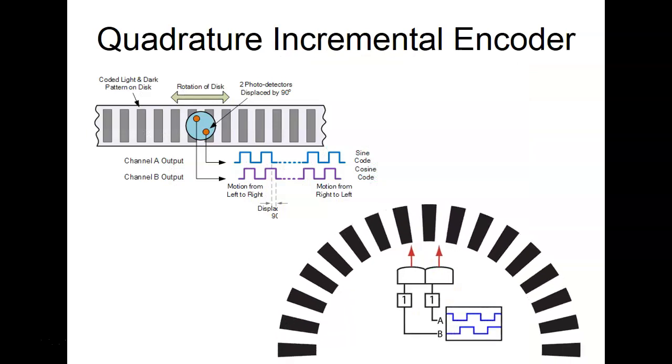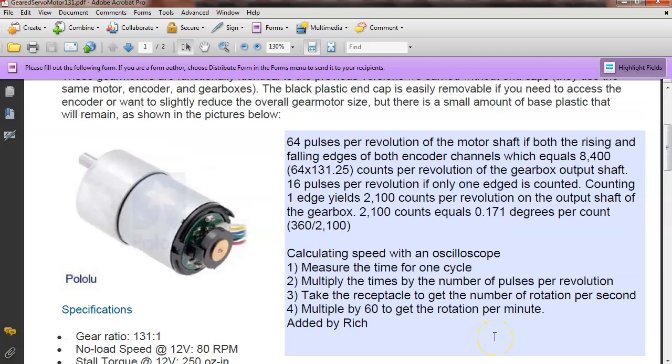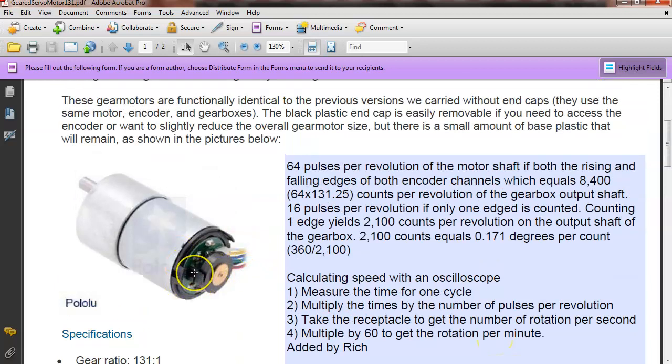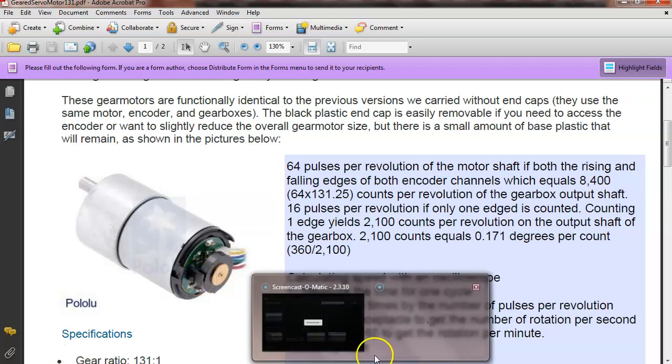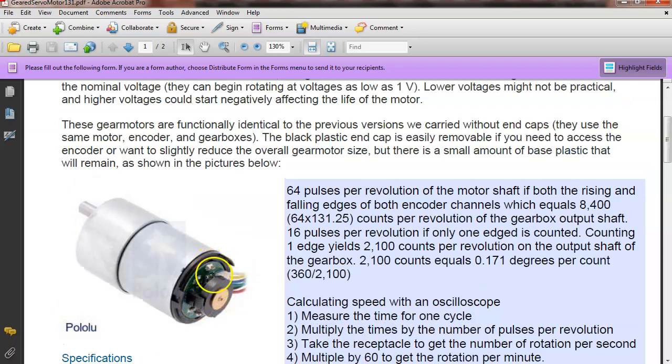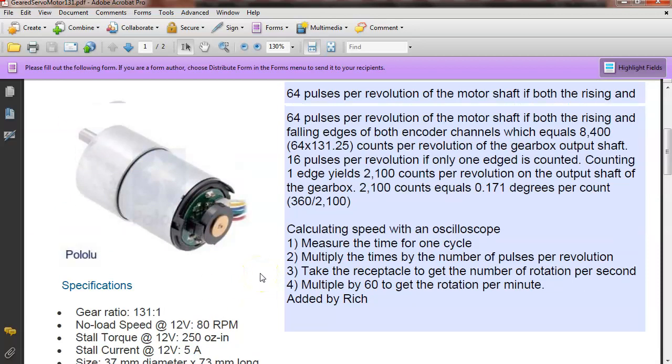This is the signal we discovered here. It's using Hall effect for the encoder. We'll look at that. That's one of the things that senses a magnetic field. This thing is turning, the poles are constantly changing, and then we have a sensor that picks up the magnetic field. Now this is going through a gearbox, guys. So this is the drive out here.